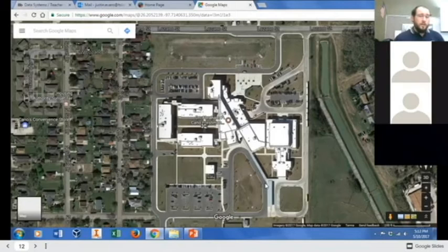And you calculate based off of whatever the city requires of you. So in Harlingen, if you're going to build something new, you're required to detain what's called a 5-year storm worth of water. Talking about a decent storm. 5 years roughly means a storm probability intensity where every 5 years you might see this level storm.